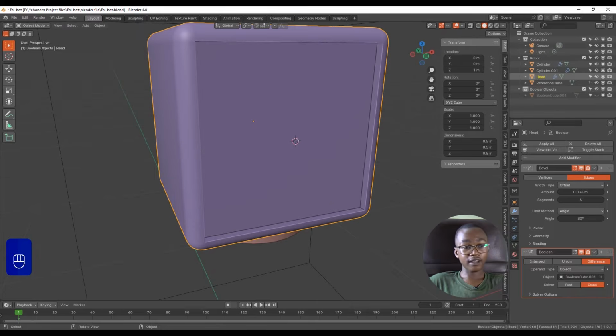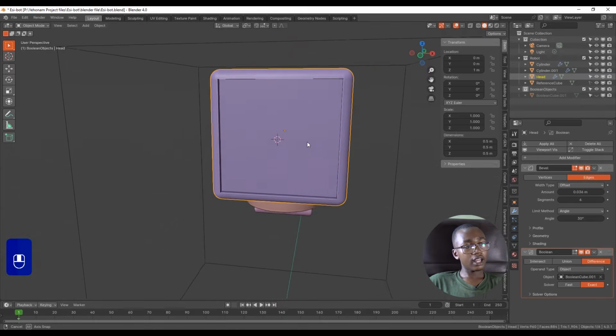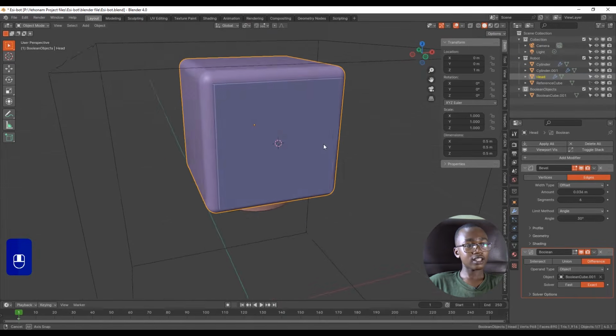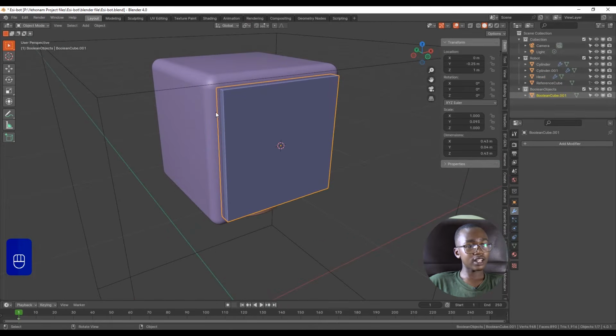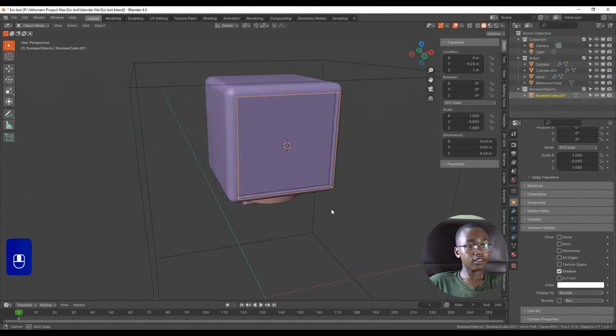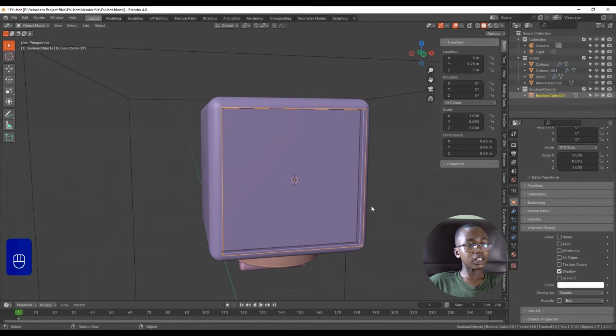If yours is not appearing, you may have to change the solvers between fast and exact. At times that helps solve that problem. I don't know about you, but mine looks too big. I would like to edit this whilst we are able to actually see this. All you can do is just display it as bounds. Yes, and that should help.